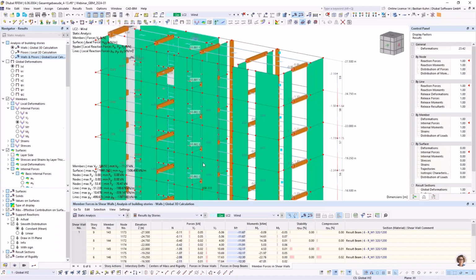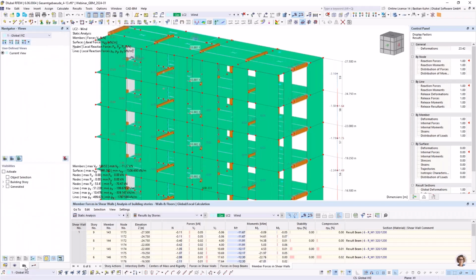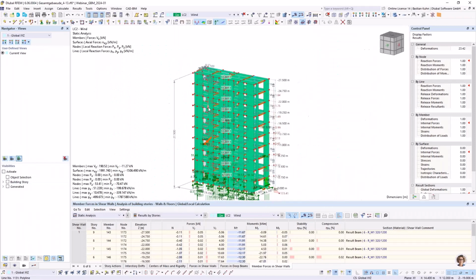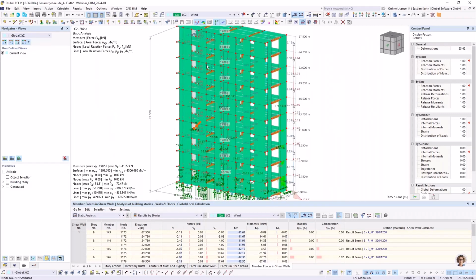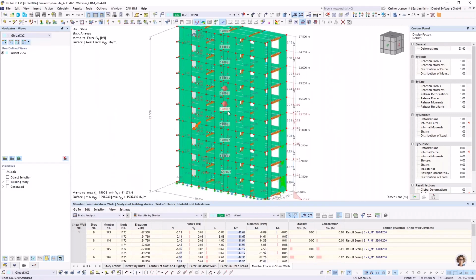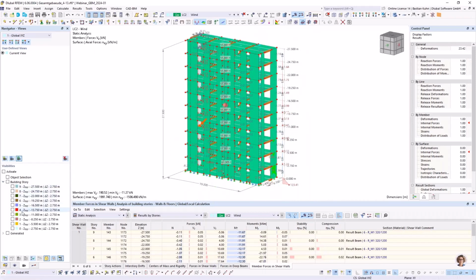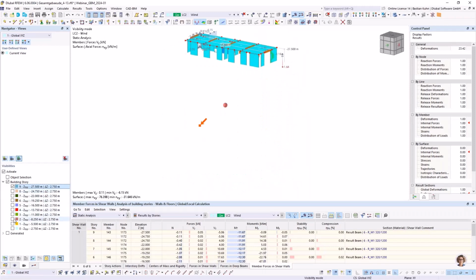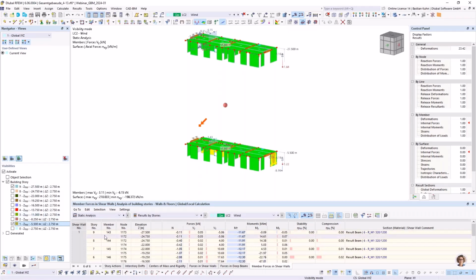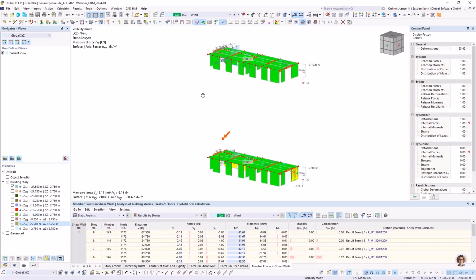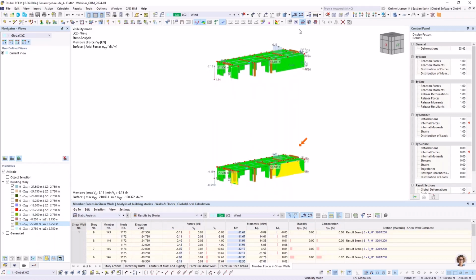All right. Then whenever you have used visibilities, it's also nice that the building model add-on generates stories for you. So you can always say, okay, I'm activating story 9 and story 1. You always have it directly automatically generated and can work only in this specific story. So that would also be possible.